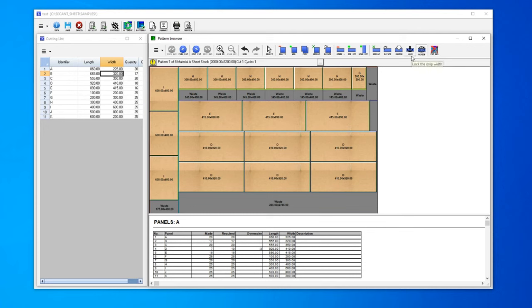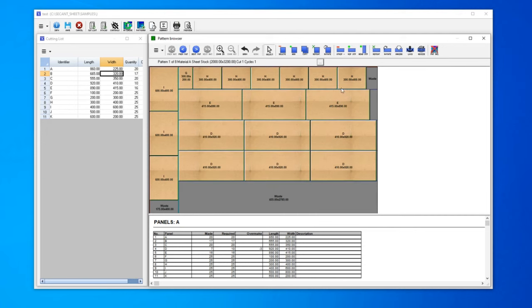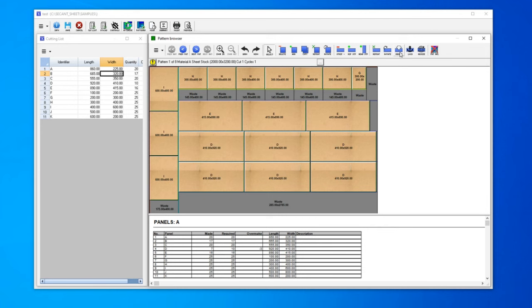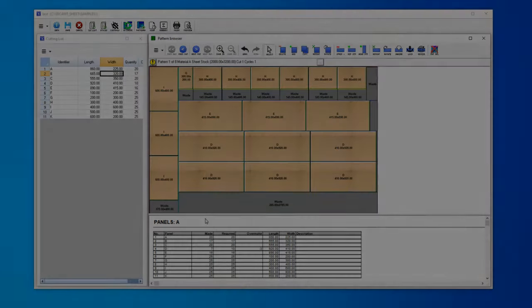If we do not choose to lock this strip, any further operations made onto the strip will result in the default setting of the strip being shrunk around the contents. For example, if I move this piece to the beginning of the strip, it will then shrink back to the minimum possible size. If, however, I lock the strip, size is maintained during any operations I make on it.